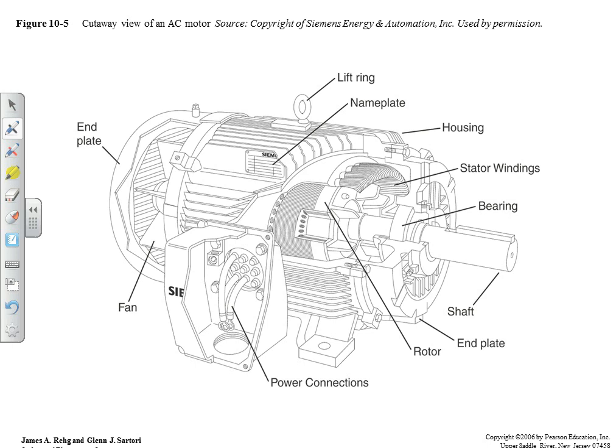And that's because of the marine environment, the saltwater environment is causing corrosion and things. If you don't do that, then by the 10th year, you're going to have motors out of commission that won't work. So you do it every 5 years, because if you waited too long, that next 5 years you'd have motors burning up.